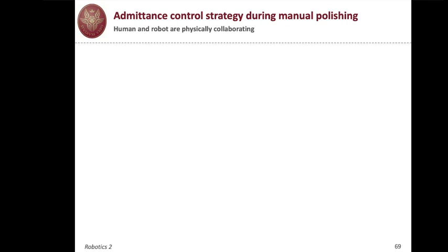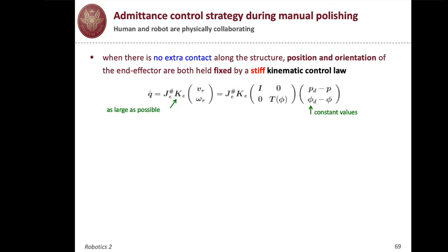Now, with this, we have isolated this. What do we do with this tau C? And more than that, why should the human operator push on the structure? Okay, so this will be clear from our operation next. But first, let's see how we control the UR10. Now, the UR10 has no fast research interface. So although we have identified the dynamic model of this robot, we are commanding only velocities. We rely on a low-level controller for the execution of our kinematic command.